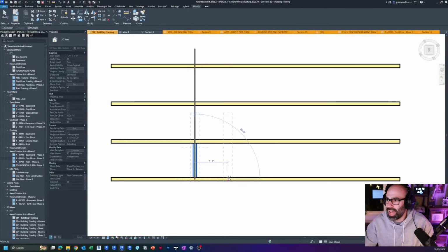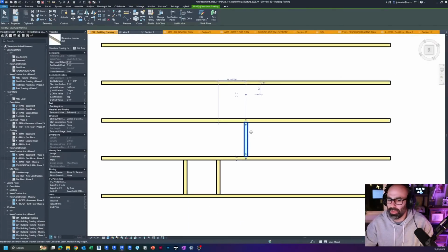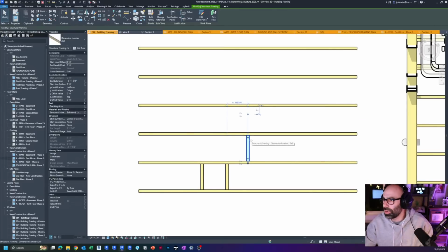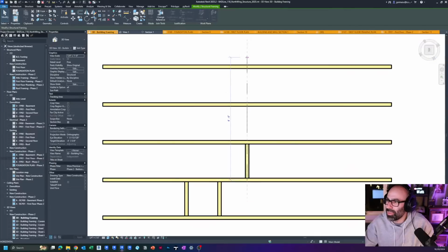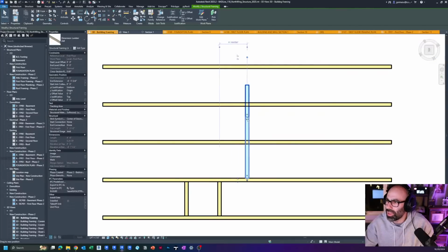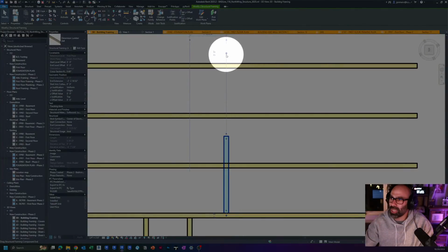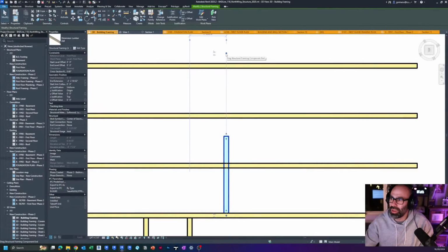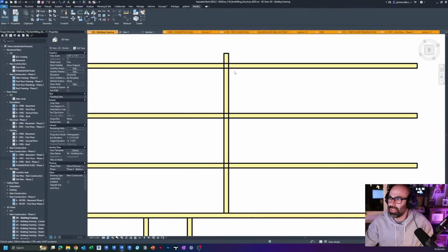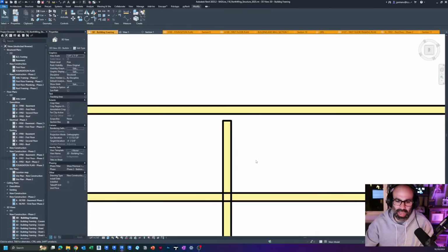If you copy this beam around the project and you start messing with it, this thing will destroy you. Because you'll notice if I pull the extension, watch what happens. This goes with it, but then I go like that. And you're fighting between the actual point, which is the framing end of the component, and the geometry extension, right? The extension exists for a reason, for things like coping and other stuff like that. But as much as possible, I urge you to try and keep your extensions to 0 and try your best to move beams using the dot and not the arrows.